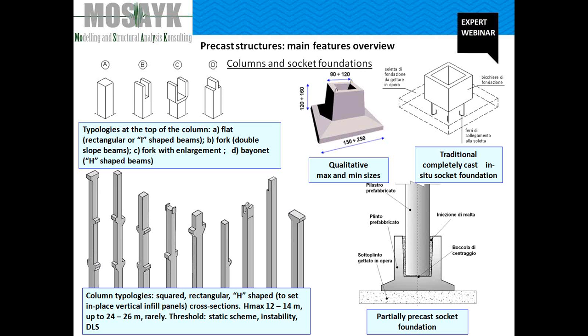A problem we should consider with particular care is the connection between the reinforced concrete tie beams and the socket-based foundation. This is because of the demand by precasters of simpler techniques without cast-in-place concrete, due, as we have seen before, to the increased use of unskilled labor and the increase in time. In addition, despite the simplified design method, the tie beams usually are also the support for the vertical panels.